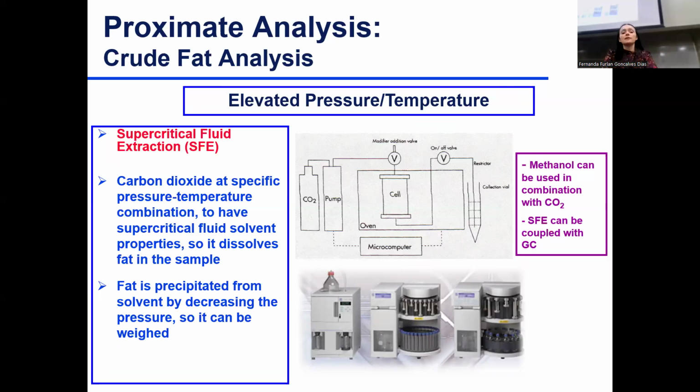Not as common because it's a little expensive, but it's being used more and more. Supercritical fluid extraction. So here you work in the supercritical state. Carbon dioxide, at regular temperature and pressure, is a gas, right? If I apply a lot of pressure and temperature, I can move it to a supercritical state. You see it at the end of the equilibrium phase diagram. It's not a liquid, it's not a gas, it's something in between that has very interesting properties, such as non-polarity. So it can act as a non-polar solvent, but it's a green solvent, which is pretty cool. So you're not using anything flammable here.